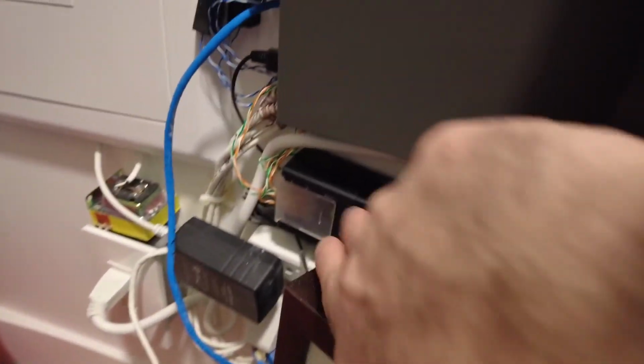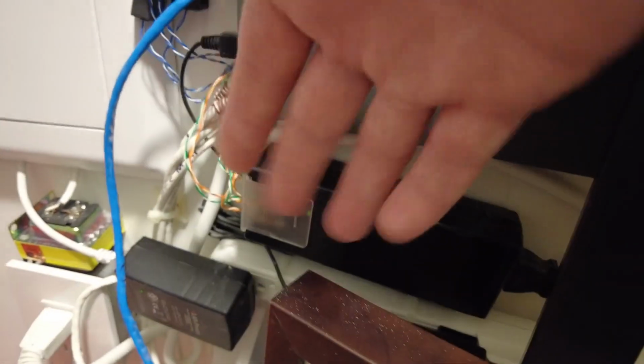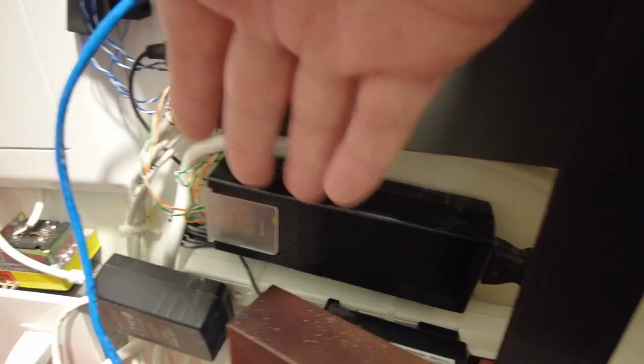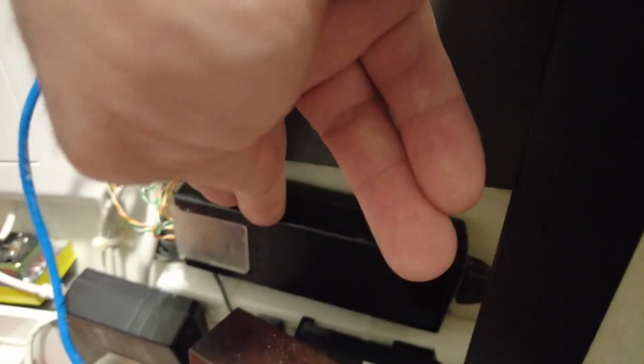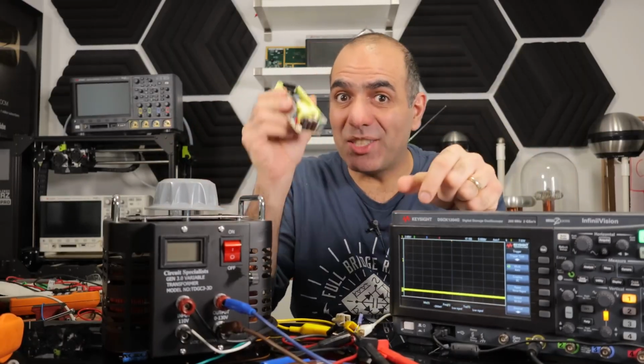Well, I did have a problem with this wall adapter here, which supplies to all my security cameras, and all my cameras were turning on and off. I cut it open and lo and behold, it was a bulged capacitor. I replaced the capacitor with a higher rating capacitor and it's been working since. Now that we know all this, let's repair a broken power adapter together.